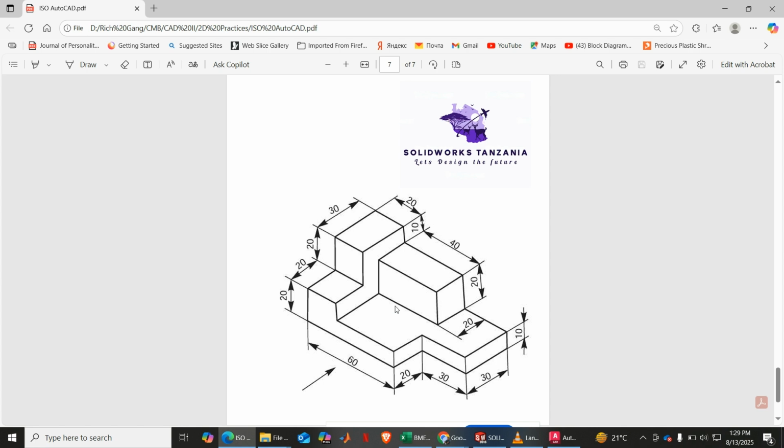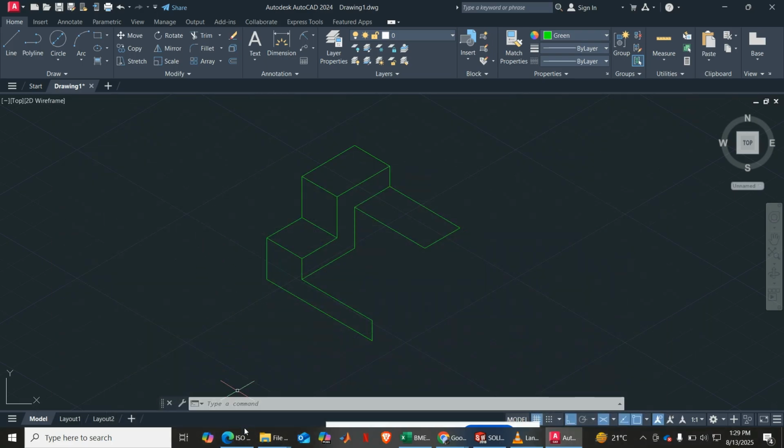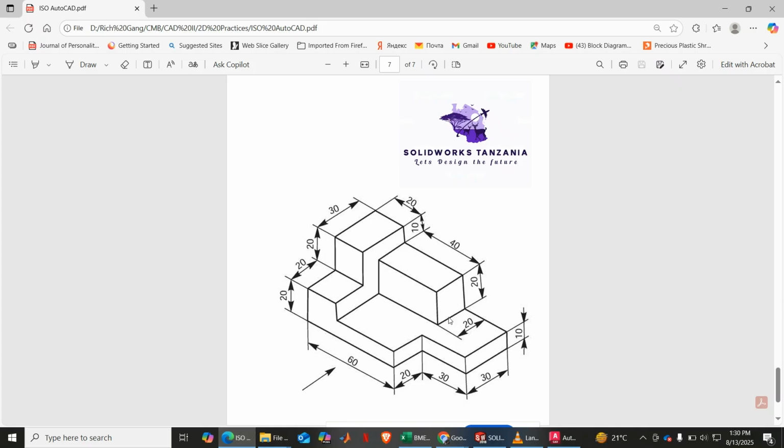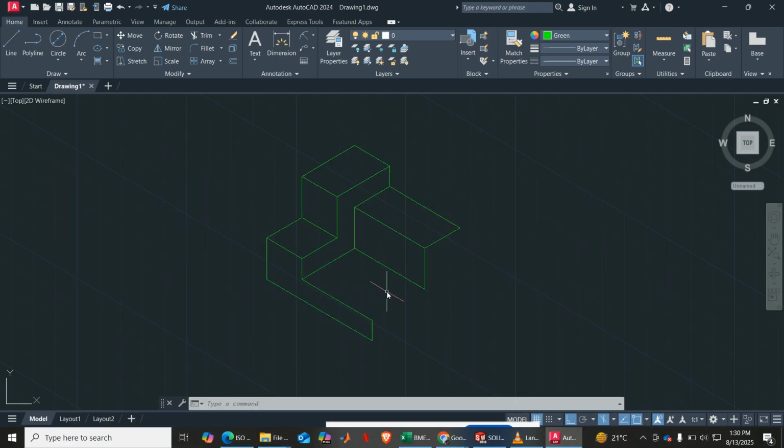Now I can draw this line here which is 40 by 20, right? 40 by 20. Oh, this is on the left side. So Control E, line from here this way 40, enter. This way let's click it to right there, escape. Again, I have this line here. This is 20 by 20, right? 20 by 20 is on the right view.